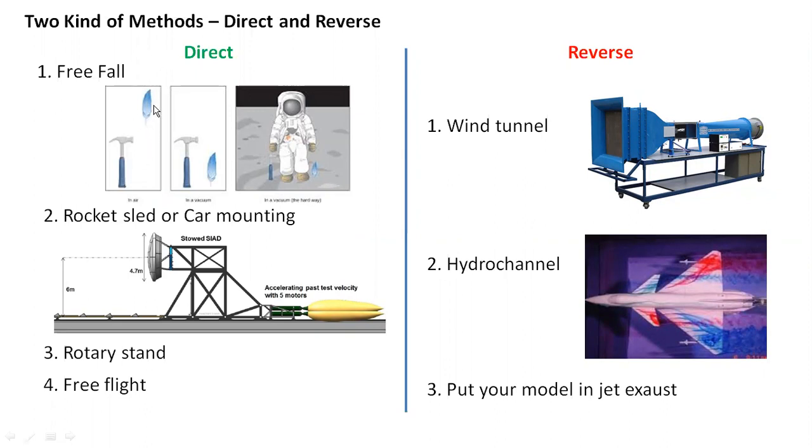And we can measure this difference in time. And this difference in time is proportionate to drag forces. So we can just take a very tall building, take different shapes of body, like a sphere, like a cube, like a cylinder, throw it down and calculate time of falling.